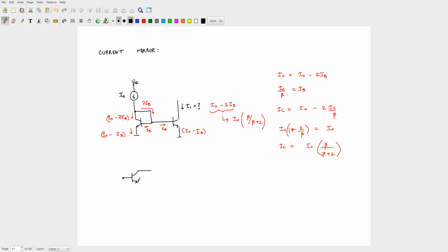We have seen this already. What happens now? You will have something like this. Yeah, right. So this is your Darlington pair. We saw this somewhere earlier in your ULN, which had these Darlington pairs, right? So if this guy had a beta and this had a beta, the net result is going to be beta squared, roughly. Okay. So if you replace all of these things by this guy, your beta will go up. So the matching between things will improve.